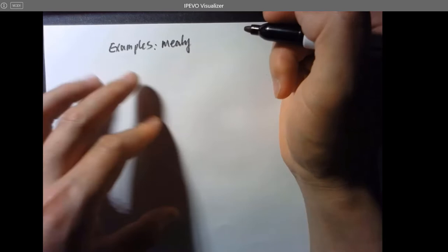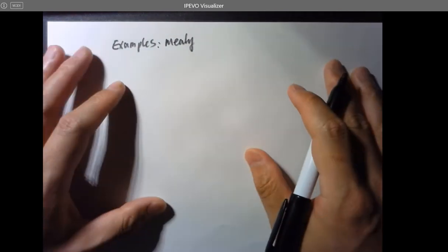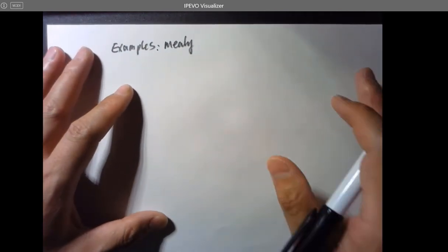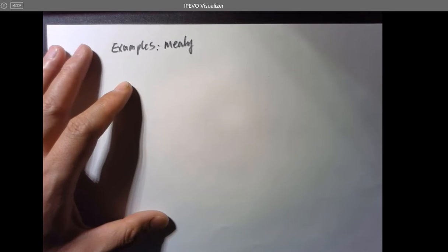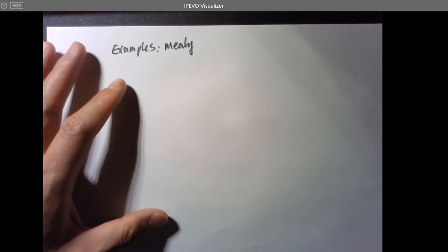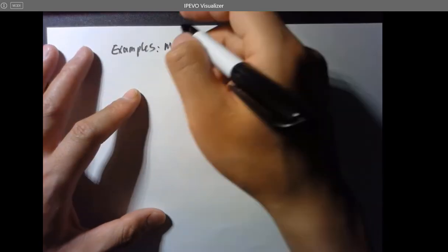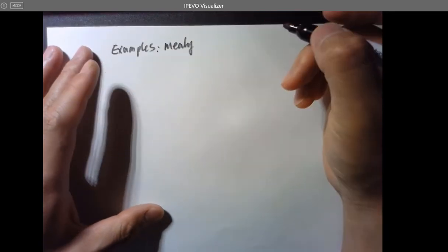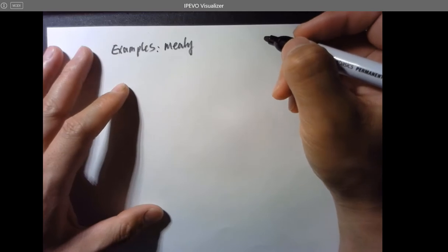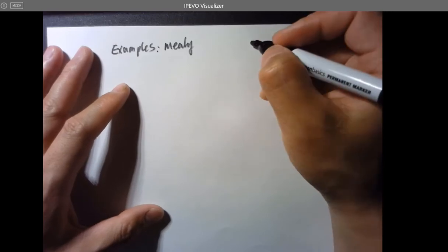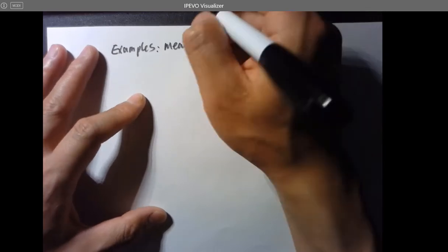It's actually super easy to identify if it's a Mealy or a Moore state machine, because you can directly see if the input is being injected into the combinational logic of the output. So let's take a look at a very similar example from the first one we introduced in the last lecture, and we just modify it into a Mealy state machine.